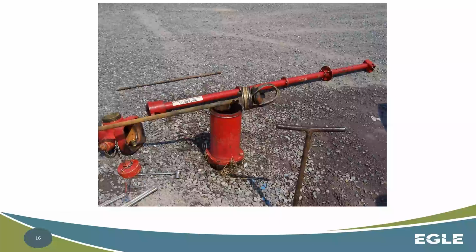So in this scenario where it was clear they were not able to get flow to close, you have to know something is up, because the pressure of the water system is pushing against the valve head, which means that it would want to close more than anything. And as traffic breakaways are, the same thing with these stems. If these stems or some portion of the stem was to break for some reason, this valve itself would want to force against the seal point and close off. So in this scenario, they should have known there was an obstruction of some sort.